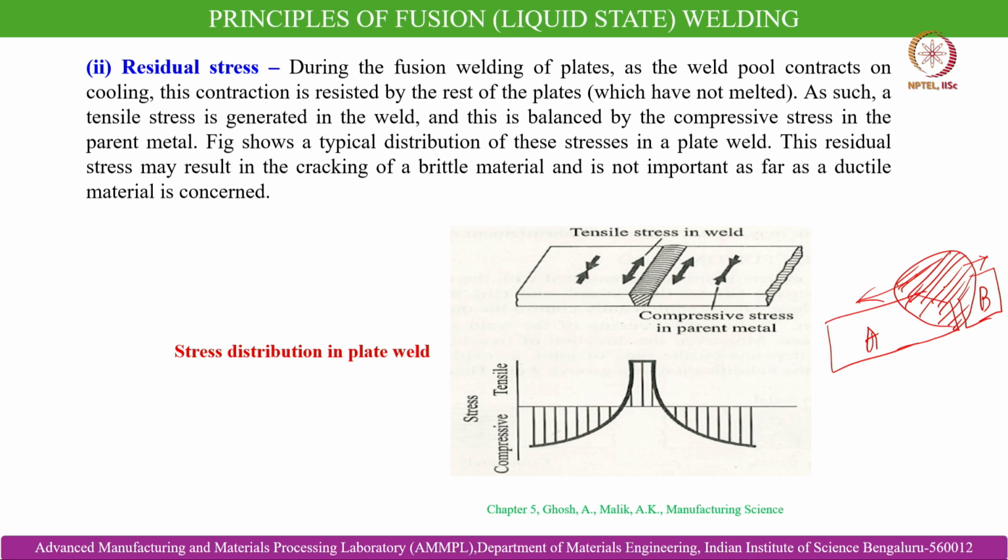Because of the tensile stress applied by the workpieces to the solidifying weld pool, the weld pool in return applies a compressive stress over the workpiece material undergoing fusion welding. So if we plot a stress versus distance plot, the stress changes sign.